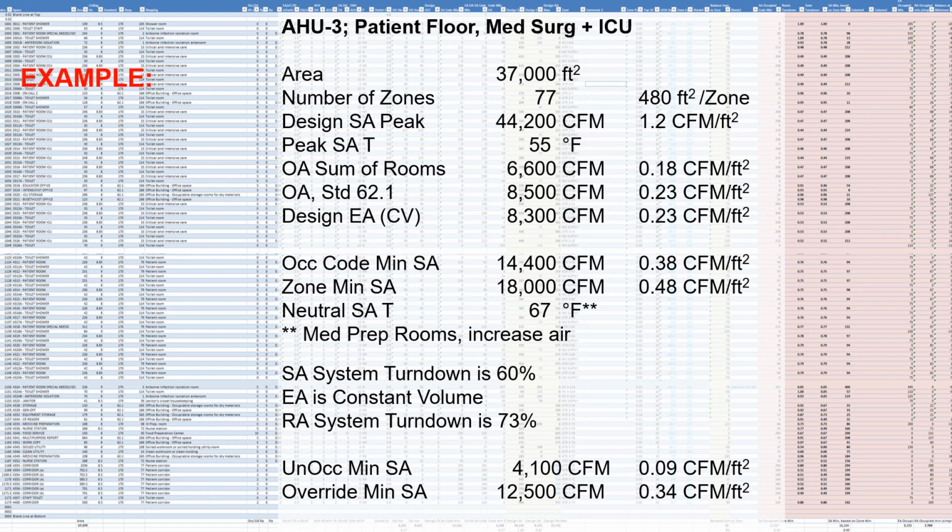And that's when you need to look at balancing around the floor and see where that return air is going, where that return air is coming from, and whether or not there is any need for return air controls. In this particular system, there wasn't. There wasn't any zone that was significantly 150 CFM per door or anything more than that.